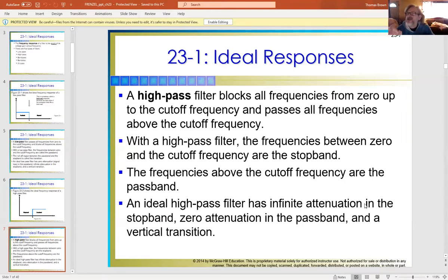That effect is attenuation, where you dampen a signal down to the point where it's unusable. You just don't have enough magnitude to actually do anything with, right? Then that would be an attenuated signal. It's literally like you started with an original signal, and if we analyzed it, there would still be a signal per se there. It's just we wouldn't be able to do anything with that. But that's typically what they mean by attenuation, where you get signal squashing.